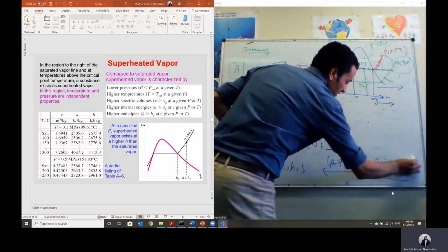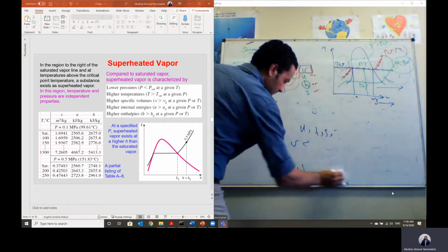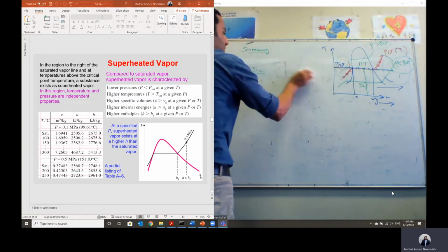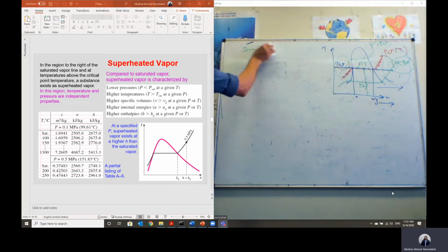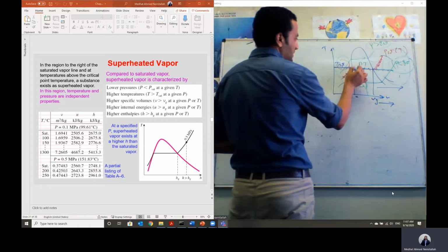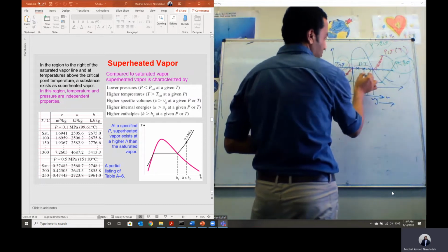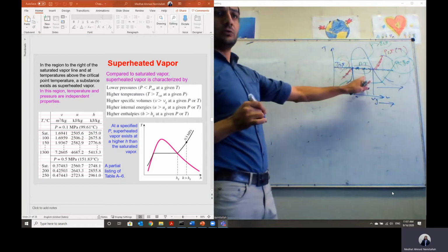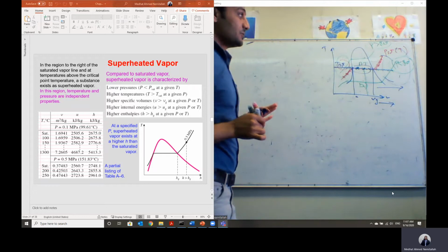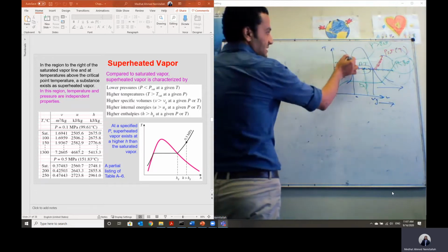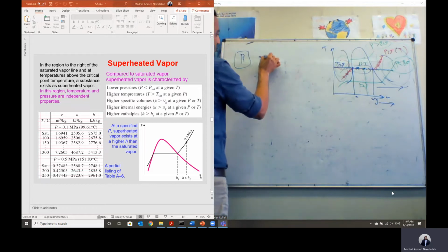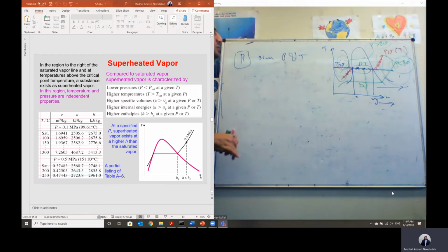Let's say pressure and temperature are given. As we said, pressure and temperature are not independent in the case of a saturated mixture. So if pressure and temperature are given, the case cannot be a saturated mixture, because all points have the same pressure and temperature. We cannot calculate the properties in this zone for a saturated mixture using pressure and temperature. So if pressure and temperature are given, the case should be either subcooled or superheated. So option B, where pressure and temperature are given.